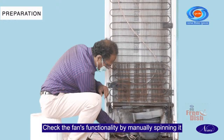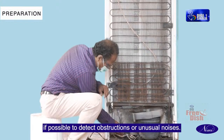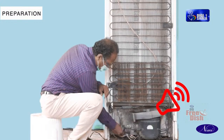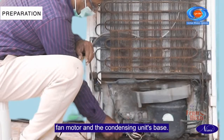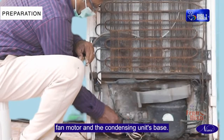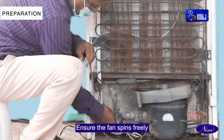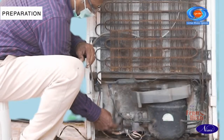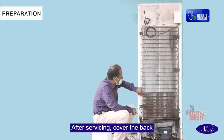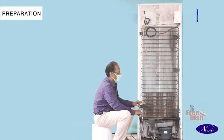Check the fan's functionality by manually spinning it if possible to detect obstructions or unusual noises. Lubricate the fan motor and wipe the fan motor and the condensing unit's base. Ensure the fan spins freely without resistance after cleaning. After servicing, cover the back and securely tighten the screws.